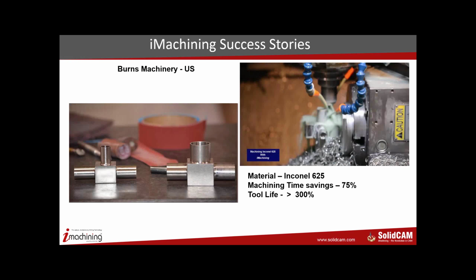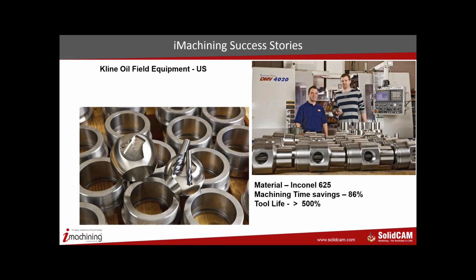Another very nice success story that you can see on our website is from Burns Machinery in the US, where we cut Inconel 625, time savings of 75%, and importantly, tool life up by 300%. Klein Oilfield, Inconel 625, time savings of more than 86%, and tool life up by 500%. What is all important here is that your tool life is going up, apart from reducing your time.